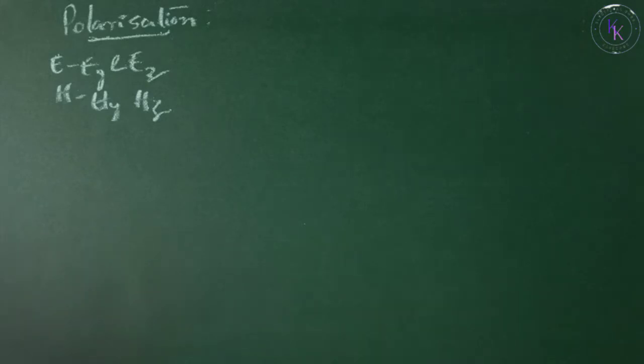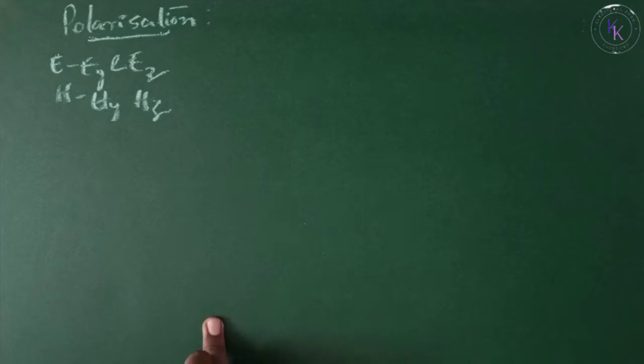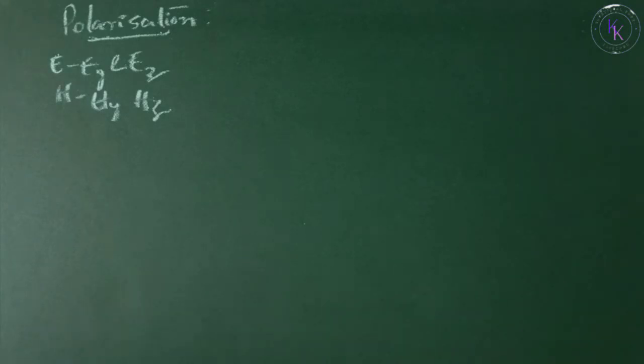Polarization means the time varying behavior of the electric field intensity vector E at some fixed point in space along the direction of propagation. If the wave is traveling in the x direction, the component EY of E lies in the y direction in one perpendicular plane, and the component EZ of E lies in the z direction in another plane, which is perpendicular to both these planes. If the space wave is sinusoidal, the variations of EY and EZ with respect to time are also sinusoidal. EY and EZ may be equal or unequal in magnitude, and they may be in phase, or there may be a phase difference between them. Accordingly, the tip of the total field intensity vector E would trace a straight line, a circle or an ellipse on a plane which is normal to the direction of propagation of the wave.